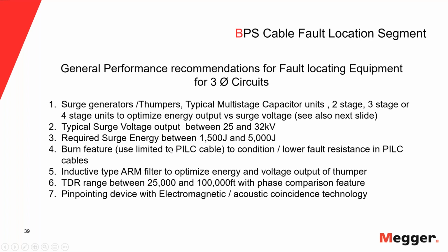And like I was saying before, it all comes together when I have a mixed cable circuit in a network, and I do the high pot because I get a high insulation resistance. I said you have to do a high pot, and if I get a high pot where it fails at maybe 20 kV, that is not a plastic cable. That is not a solid dielectric cable. That is in the paper section.